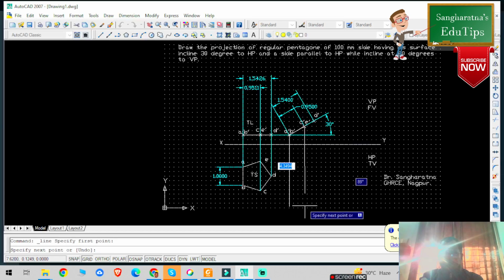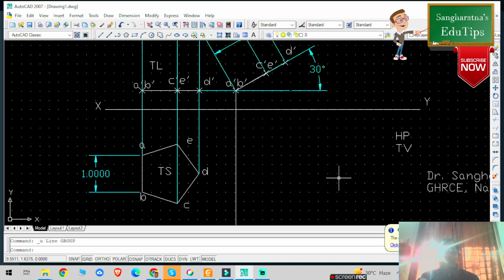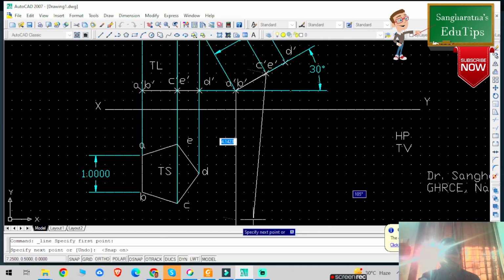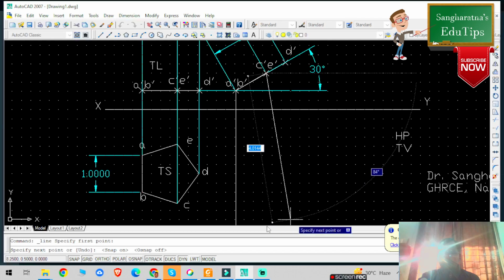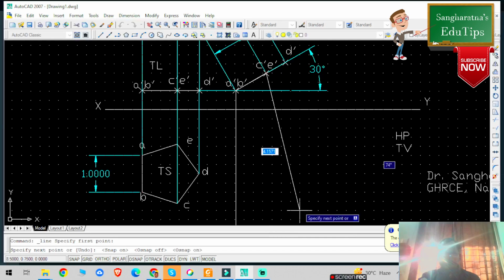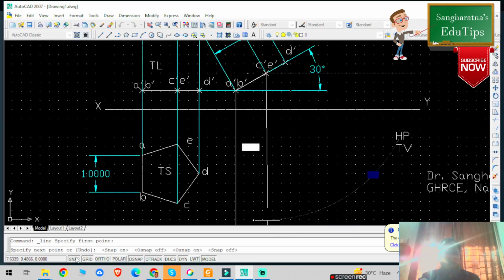Press Control Z. Right, so this is not perpendicular basically. So what I'm doing, again I'm drawing it. This practice you need to do again and again to draw the perpendicular projections. If you are not getting it, click on snap. Right, now you can draw it. Snap. I'm opening it. Click on snap.